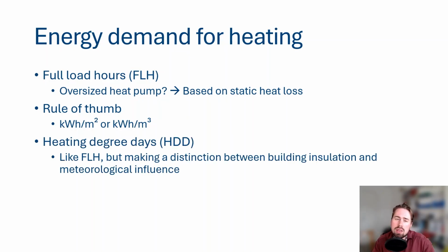Another option is to work with heating degree days. I will show an example on the next slide, but it's a little bit like working with the full load hours. Instead of taking the meteorological and the building itself into account in one number, the amount of full load hours, we can here make a distinction between the building insulation and building physics and the meteorological influences like the temperature. So what are heating degree days?